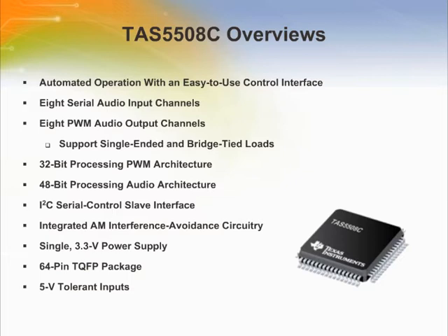The TAS5508C automatically adjusts control configurations in response to clock and data rate changes in idle conditions. This enables the device to provide an easy-to-use control interface with relaxed timing requirements.